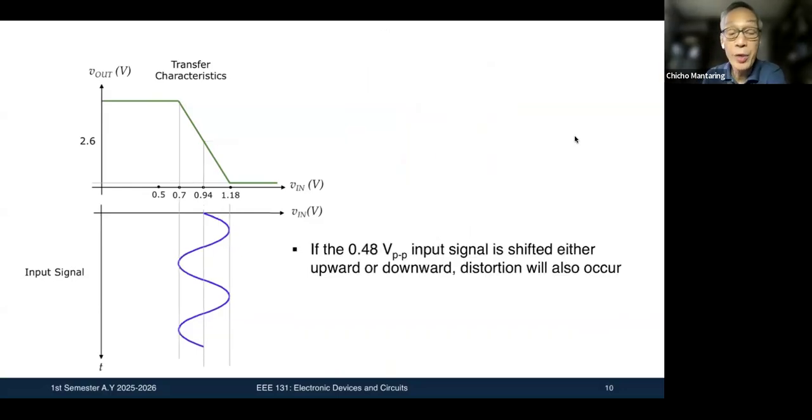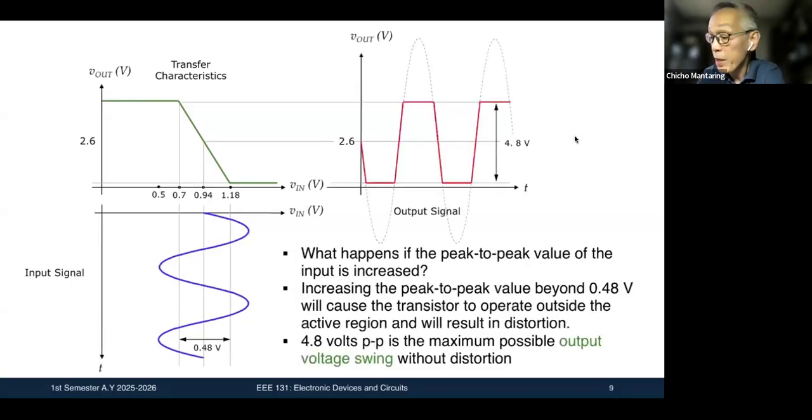What about the situation where, remember here, your input signal is offset? It has a DC component and it has a time varying component. That's why we use, I hope you remember, our standard for specifying signals that are like that. The subscript should be capital. When you have small v capital IN, that means this is a time varying signal that consists of both a DC component and a time varying component.